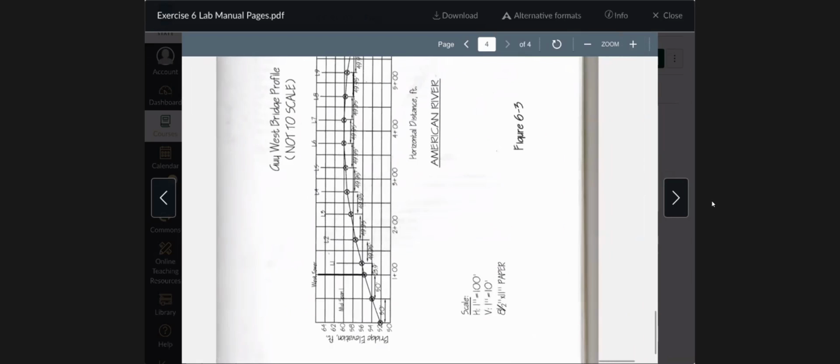First, I want to discuss the scale here. We don't use inches in this class. Well, we don't use inches to measure anything. We use decimal feet. Everybody understands that now after 4 weeks. But when you're preparing a drawing, even though you're measuring in decimal feet, when you print something or prepare a drawing, you're still using English units, inches.